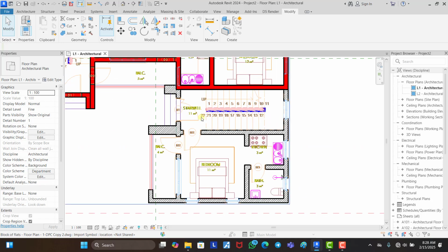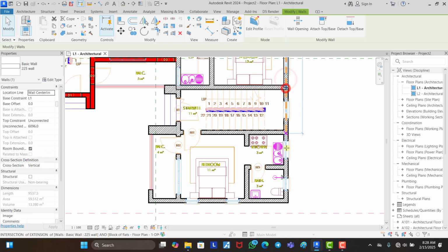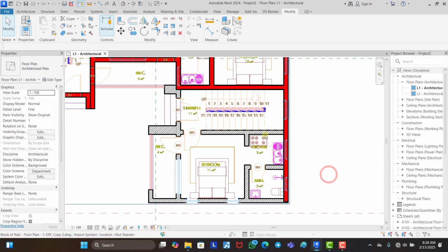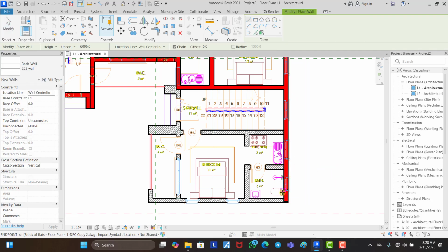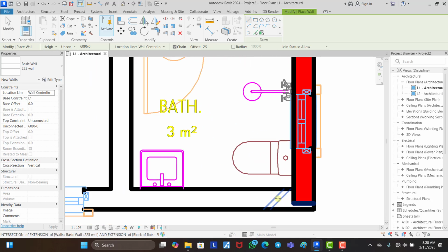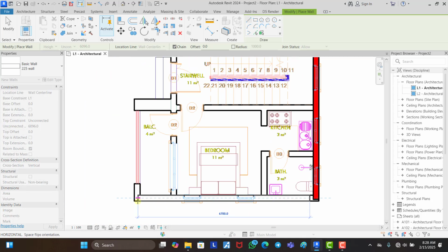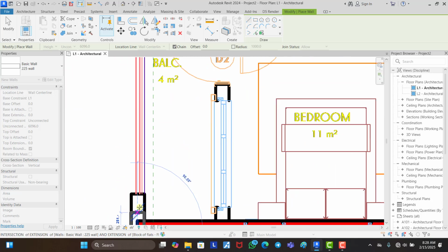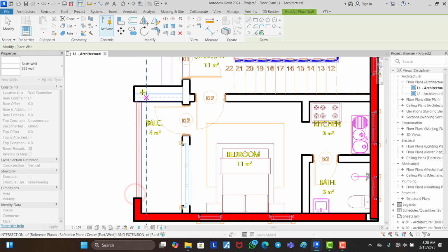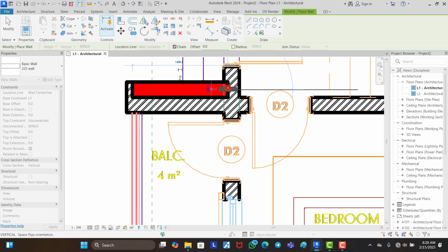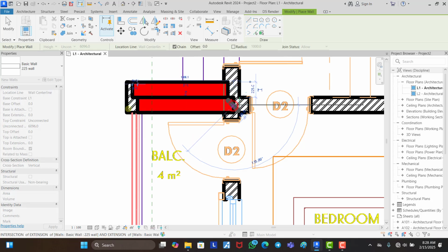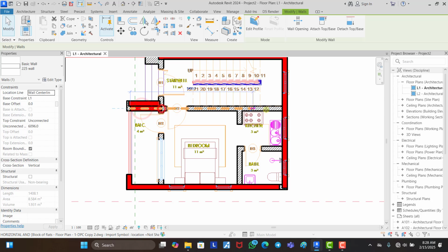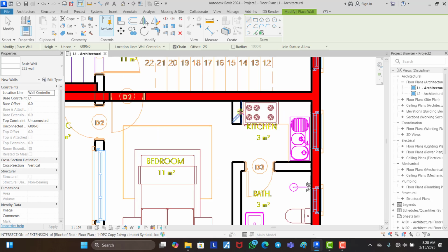Then the remaining part is here now. So we just need to continue tracing the walls out, align this here. Okay, you click on the wall, click on CS to create similar, and you align this, you draw this one. Okay, then you also draw this one to this point. Now you have a double wall here, you draw this here, and you also get this here. Okay, sorry, this one went down to the edge here. All right, good. Click on the wall, CS to create similar again. Okay, stop this at this point.